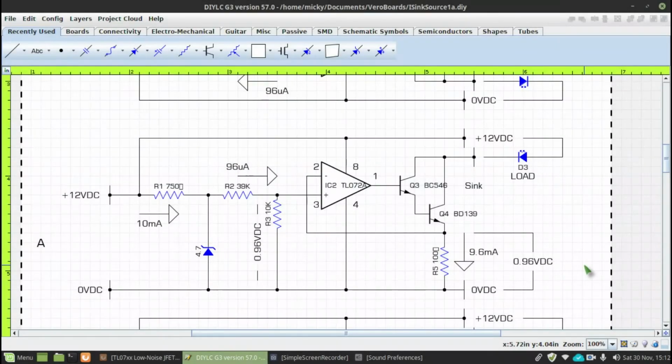I thought I would just show you the original circuit that we developed for the current sync device, and you can see it there. We've removed the base resistor of Q4. If you remember, we changed R3, which is a 10K, to a 10K potentiometer, and this effectively is an NPN configuration on the output here with negative feedback in unity gain.